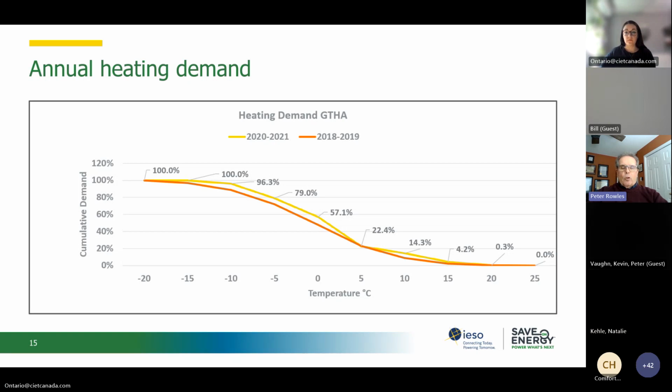The two graphs here show the most recent cold winters and mild winters. It shows roughly that about 30% of the heating season is in the small range around freezing. It is important that the selection and sizing of a heat pump considers this factor to ensure the heat pump works for most of the heating season. If not, the occupant will be spending more money on fossil fuels or electricity, depending on the backup system.